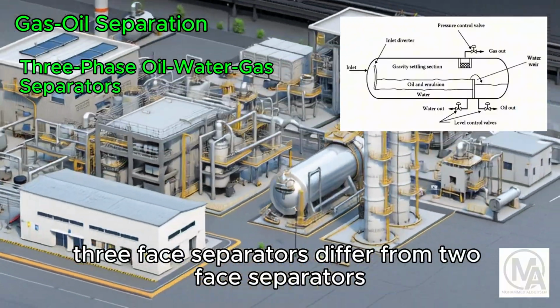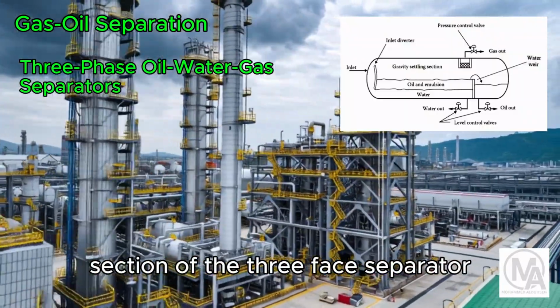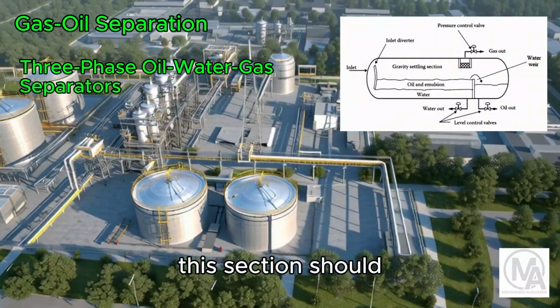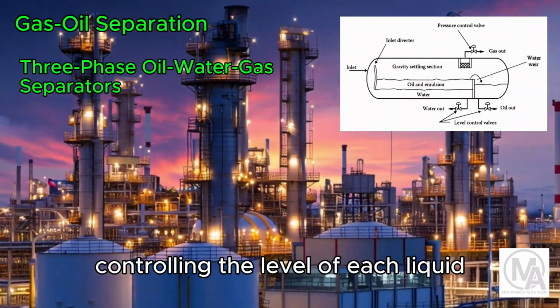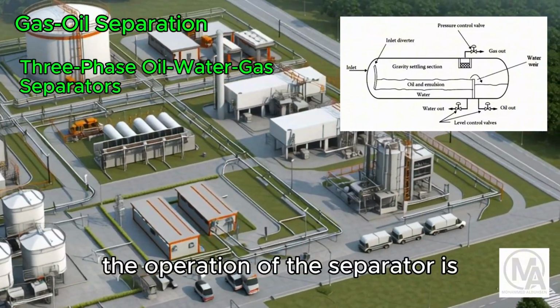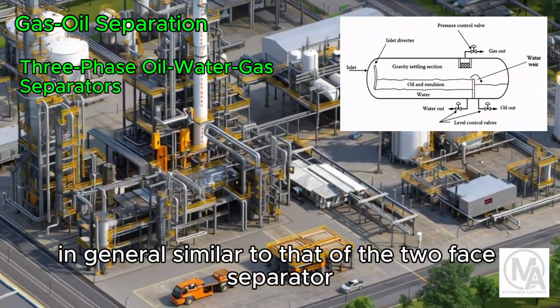Three-phase separators differ from two-phase separators in that the liquid collection section of the three-phase separator handles two immiscible liquids, oil and water, rather than one. This section should therefore be designed to separate the two liquids to provide means for controlling the level of each liquid and to provide separate outlets for each liquid. The operation of the separator is, in general, similar to that of the two-phase separator.